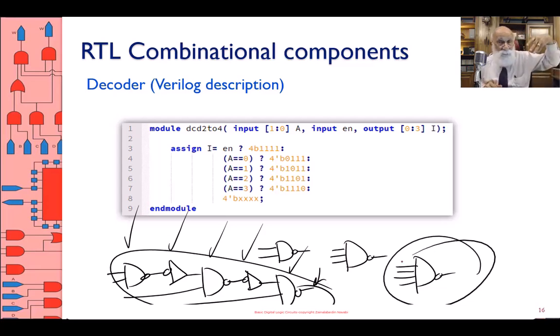Whereas if I were able to do 4 transistors in series, I'm not saying the 4 series transistors are going to have the same delay as a 2-input NAND gate, but the delay is not as bad as the cascading that I'm showing on the left-hand side. So what I'm saying is cascading is good because you take one small circuit and build bigger and bigger and bigger. There's no limit to it.